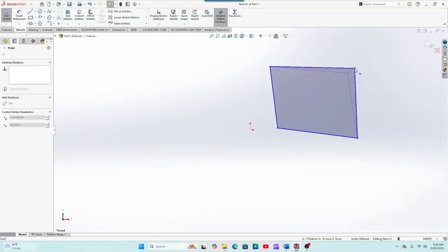All right. So the main thing when you're sketching in SolidWorks is that you need to make sure that you lock everything into place and you have a fully defined sketch at the end. Because if you don't, and you go back in and do some editing, you're not paying attention, maybe you inadvertently move a corner even just a little bit, it can throw your sketch out of whack, and then any features that you have after that point will be affected. It can cause a cascading series of errors all the way down based off of everything that you've done after that.